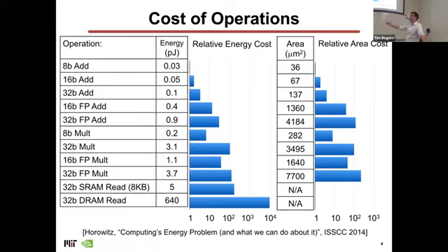So that helps improve performance. If I look at the size, these are all actual taped out numbers in real technologies. This is by Mark Horowitz, who's a professor at Stanford. This data is fairly old, but the ratios still hold true today, even on modern technologies. Your 32-bit floating point mult is going to be about 7,000 square micrometers in the particular technology that they're studying. And if I can bring that down to an 8-bit mult, again, you've got an order of magnitude reduction in the size, which in theory is an order of magnitude increase in compute for the same area budget.